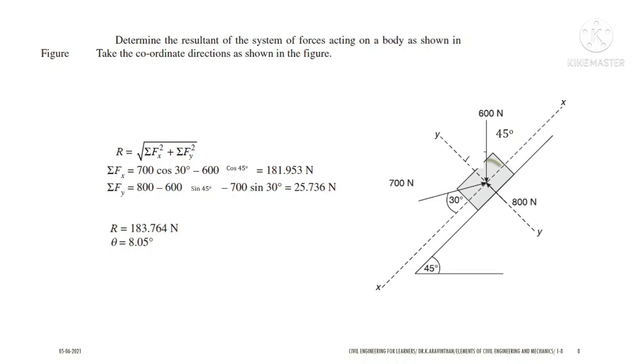After that you can straight away use the resolution of forces formula. To find the resultant, you have to use the summation of Fx squared plus the summation of Fy squared. If you take the root of that, you will get the resultant, and you get theta using these values. So straight away you can resolve all the components vertically and horizontally with respect to the axes, and you can find the solution.